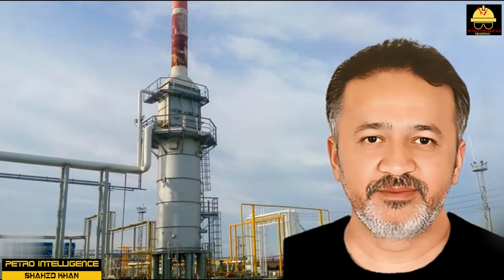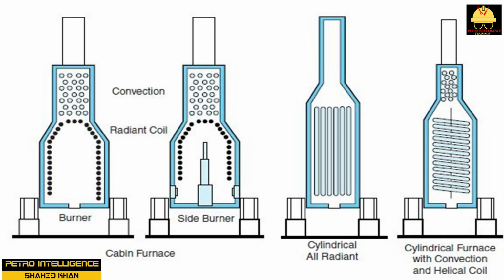Cylindrical furnace. Another very popular direct-fired heater design used by industry is the cylindrical furnace. The simple cylindrical furnace is engineered to utilize the radiant heat that emits from the burner at the bottom center of the furnace. Heat transfer is primarily radiant unless special options have been added. The cylindrical nature of the furnace enhances draft from the lower radiant section through the optional convection section and out the stack. The vertical tubes are typically composed of alloy steel.